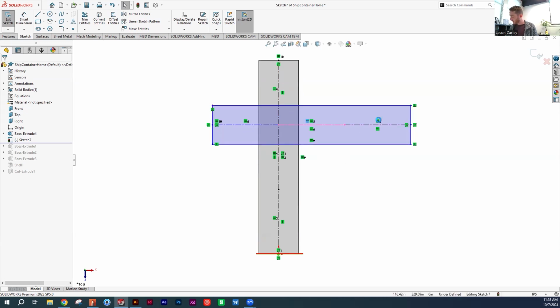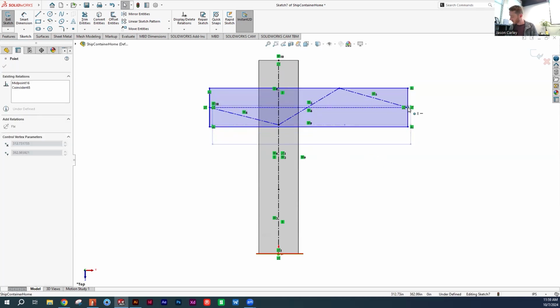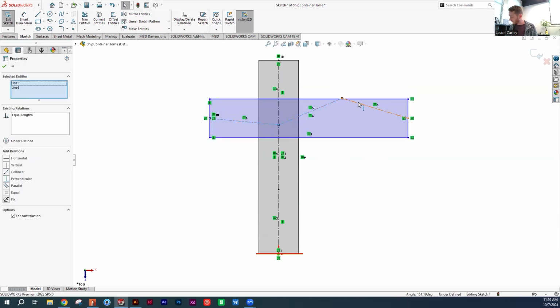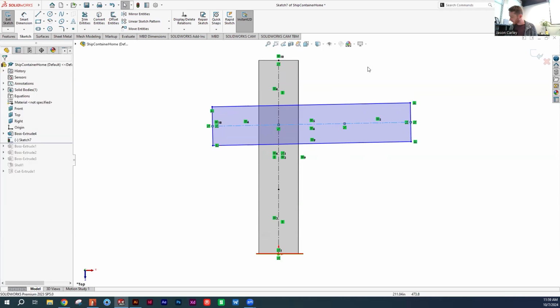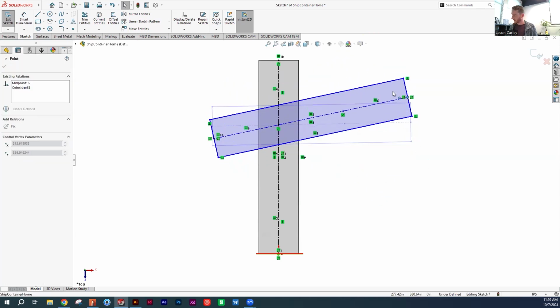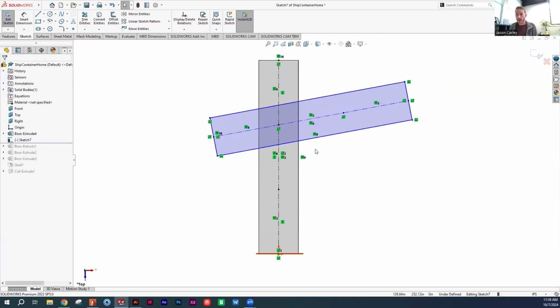These have horizontal relationships, so I can delete these. And once I've deleted all horizontal and vertical relationships, I need to make this collinear. Okay. I should be able to swing this around. Now I have a dynamically changing angle of these two, but I've set them all to equal. So I only have one set of driving dimensions, and that's in the first sketch, the first object. I hit check,